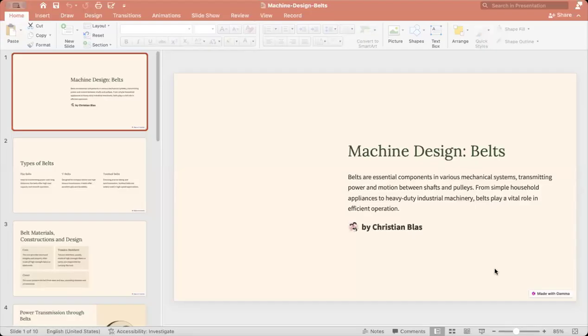Good day, class. As we discussed last meeting in regards to belts, belts are flexible bands that connect pulleys or convey materials by transmitting motion. A belt is under FPTE, or the flexible power transmitting element. The uses of belts are, of course, power transmission, conveying service, and elevator service. We have two types of belt arrangements: open belt and cross belt.